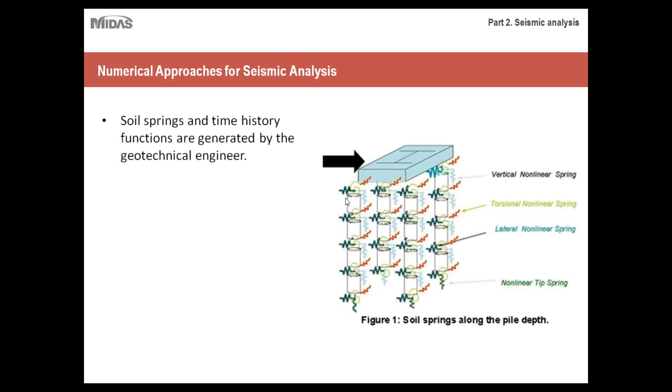So for example, just imagine a bed spring pushed up against like a cinder block here, or a tube. If you were to apply a force to it, that spring would oscillate. So just try to imagine it that way. That's why they're called springs. These spring elements take into account the oscillating behavior of how, for example, if you apply a seismic load to this pile foundation, it's going to shake back and forth. So these soil springs would take into account that type of behavior.